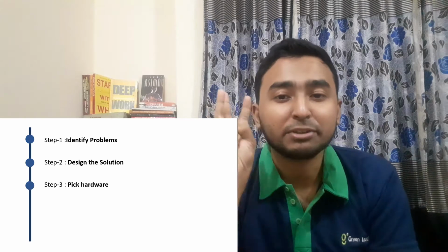Now, step number 3, choose the hardware. We have previously discussed this, right? We can follow the checklist and pick the right hardware. So, as I have told you earlier, I'm deciding on a sonar sensor for this. I am deciding to go with the MQ2 sensor for detecting smoke, and the presence of clogged water will be sensed by using a voltage divider circuit.